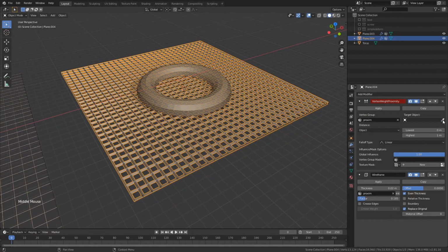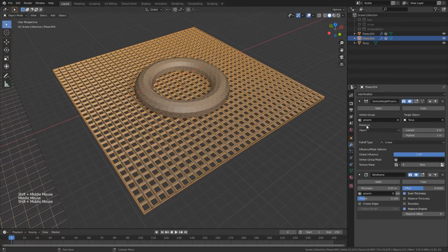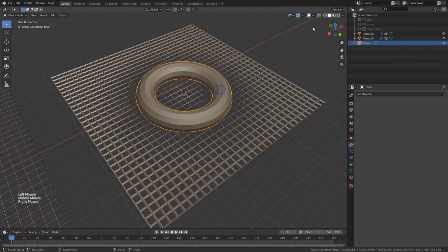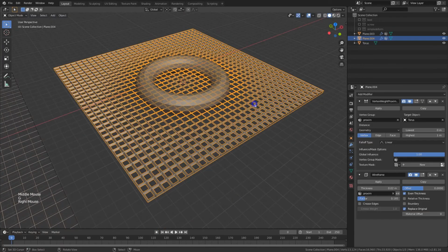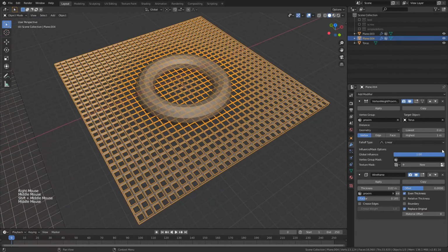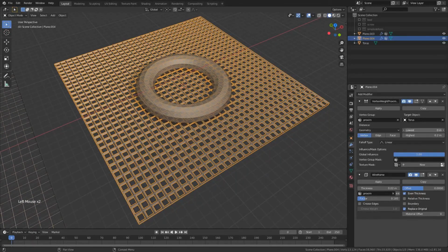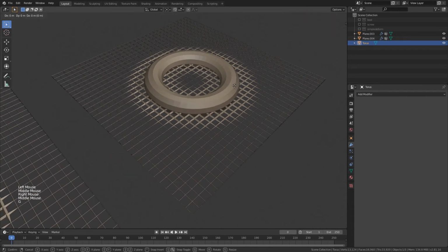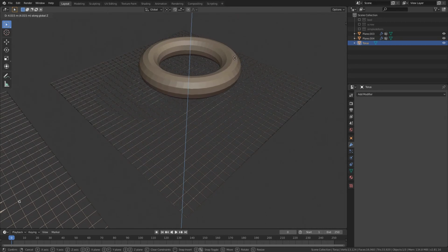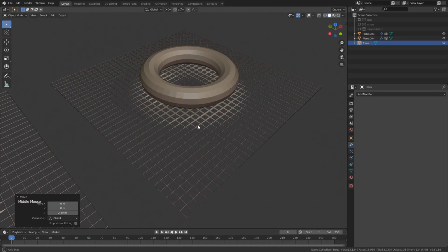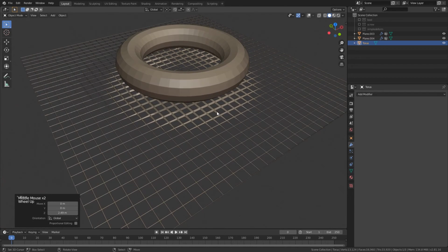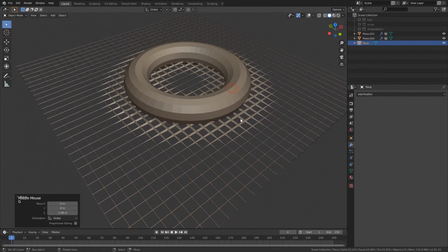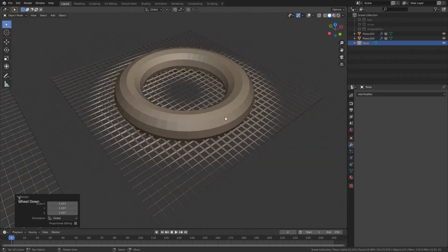Like, let's say if I pick the target object and define this torus, alright, and change the distance to geometry. Now you can see, okay, to increase the visibility more, I'll change these parameters a bit. Now what's happening is, when this object moves close to this object, the weight paint of these vertices is becoming stronger, and it's working in approximation with this object.